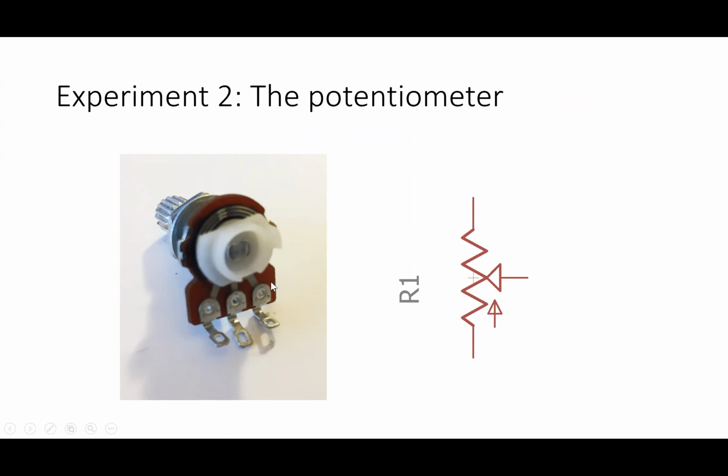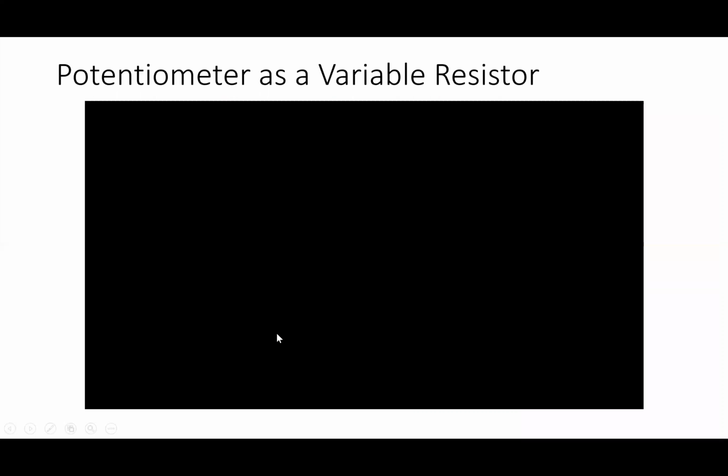So here is a potentiometer with the case removed. There's the shaft that moves the contact here. This outer contact here goes to a semicircular carbon track that goes all the way around to this other outer contact. The middle contact goes to this wiper here that has a little spring-loaded pressure pad that sits on this track at some point determined by this shaft.